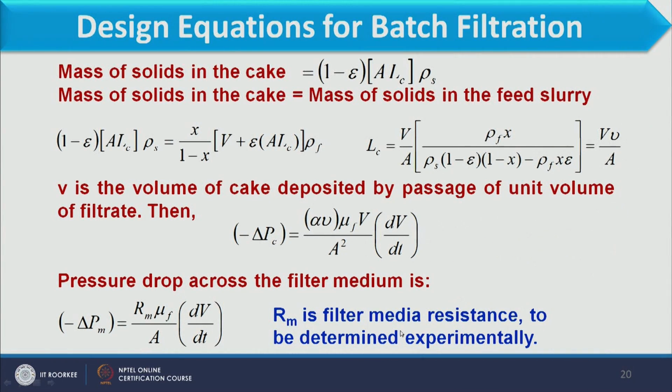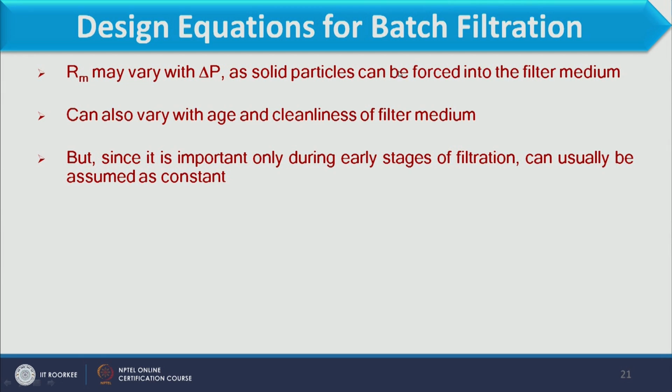So Rm is basically the filter media resistance, and it should be determined experimentally. Now we will see a few factors about the filter media resistance, that is Rm. Rm may vary with pressure drop, as solid particles can be forced into the filter media. So obviously when particles enter the filter media, the Rm value will be affected. So we can say that the Rm value will be affected by the pressure drop, because at high pressure particles will enter into the media.